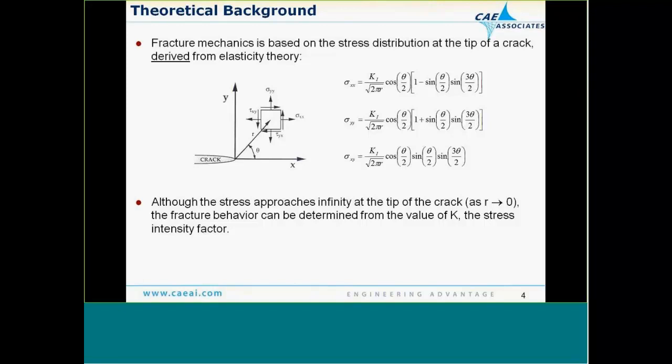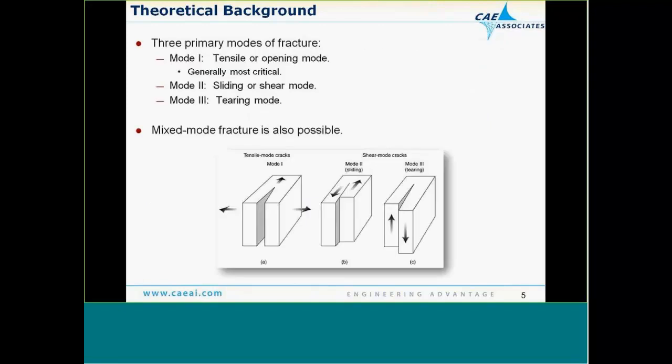That is a function of the crack geometry and the applied loading, and that stress intensity factor is the key in linear elastic fracture mechanics. We can compare that to the fracture toughness of the material to determine if the crack will propagate. So we're accepting the fact that the stresses are infinite at the crack tip, but we're using the derived expressions to calculate this stress intensity factor.